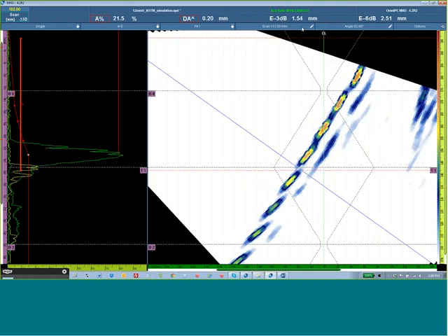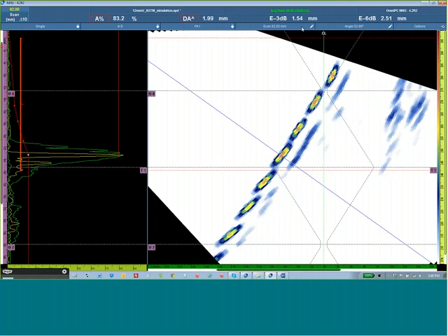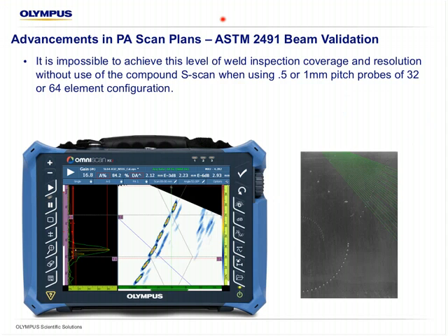Lower frequency probes or unfocused probes from farther distance will have a much larger number here for our 3 and 6 dB drop inside the envelope window, and that's a consideration for our scan plan. For most of the new weld series probes, using 5 megahertz probes as close to the weld as possible, they provide a very high resolution block.